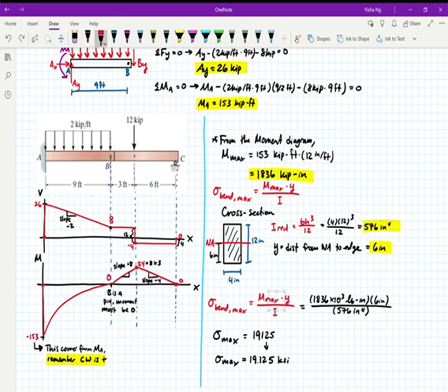So what I really should have drawn here that I didn't, that I will really quick, Cy, Ay, and I had a moment A. So these are my external forces and external moments that are acting on the beam that are going to cause jumps. So knowing that information, we're going to look at our shear diagram. I start at 0 here, but because I have Ay acting at A, I'm going to immediately jump the value of Ay. So Ay was positive 26, so I'm going to jump up to 26.